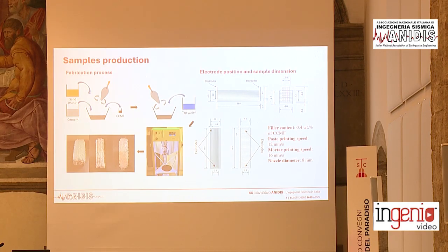We also added the water in 2 different steps, as I mentioned, and we used a different printer this time. And we printed samples with these geometries, where we first printed one with the longitudinal printing path, with the printing path, in fact, parallel to the longitudinal axis, and the other one we printed with the printing path perpendicular to the longitudinal axis.